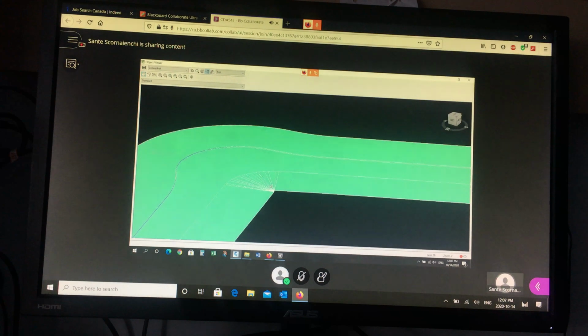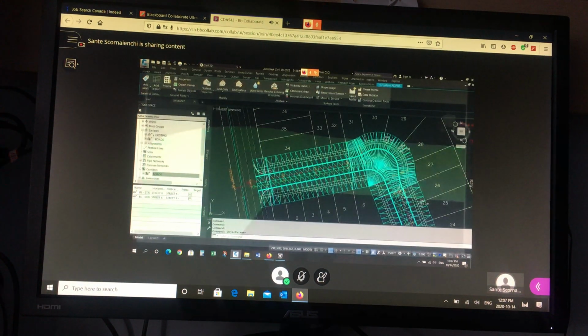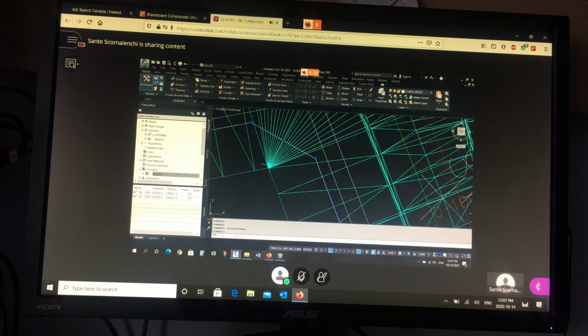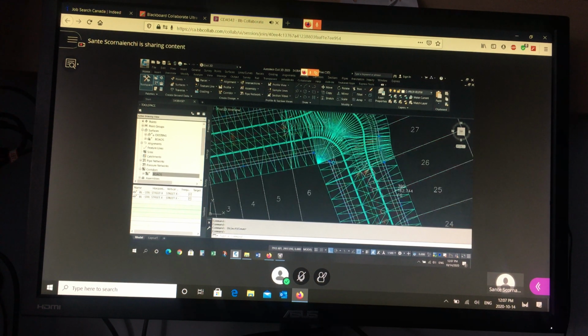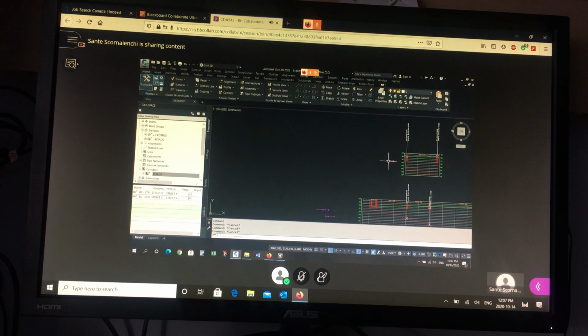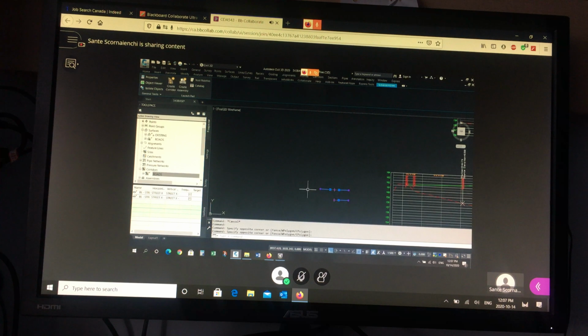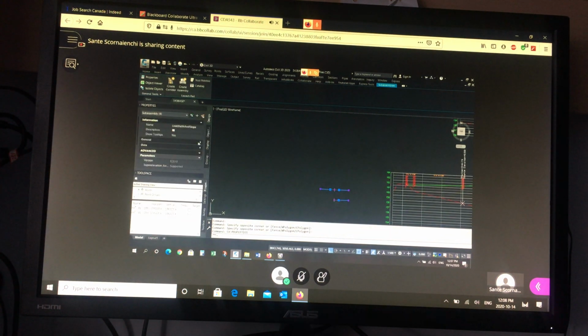And what we're going to do here is, I need an elevation at this point and at this point. So this issue here is not a big problem. This is that 10 meter wide thing. Let me go back to 6, it won't look so bad. So let me change these boulevards to 6 instead of 10. A little bit wide, doesn't have to be terribly wide.